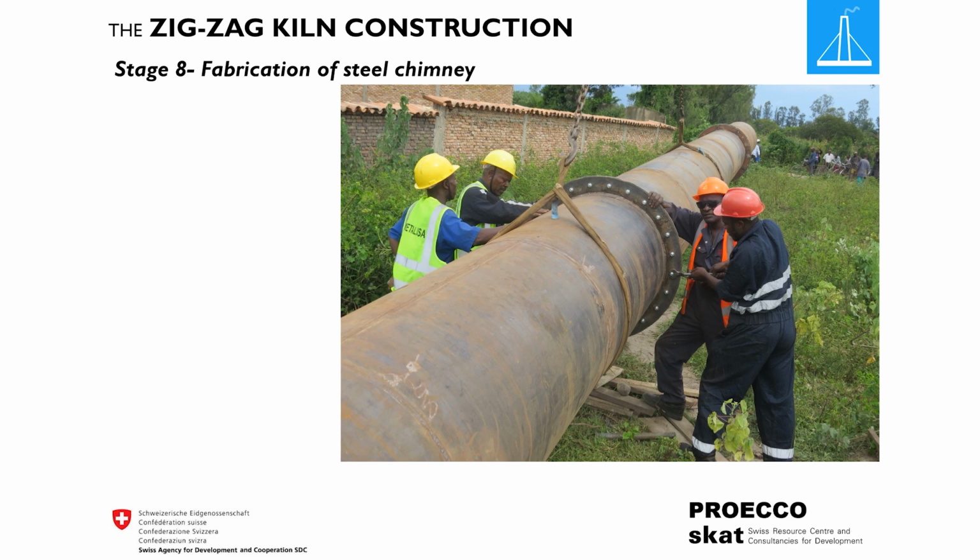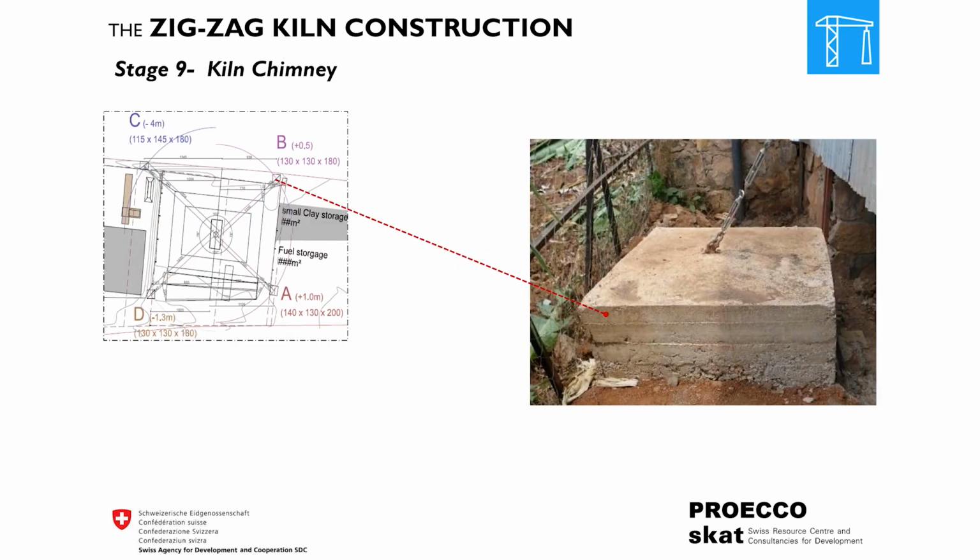In natural draft mode, the steel chimney is made from non-corrosive material such as corten steel pipe, or any other non-corrosive material depending on availability, design, and investment decision. 4 concrete columns are casted at specific corners for anchoring the chimney to the ground. Stage 9. Kiln chimney erection.